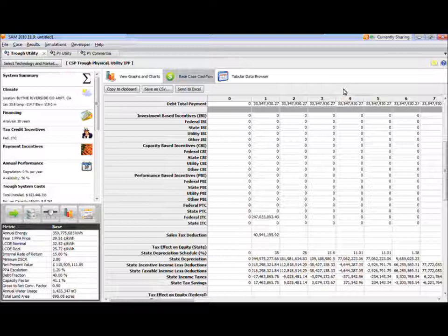When you model a PV system using the Sandia inverters, SAM does a check before it starts simulations to see if the inverter and array are properly matched to the degree that it can, given the information that it has. And so it uses that VDC max and IDC max value in that pre-simulation check.